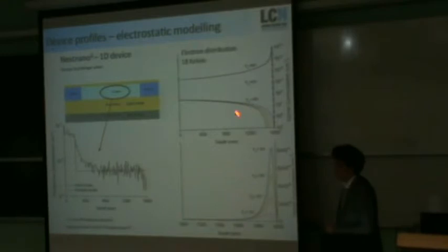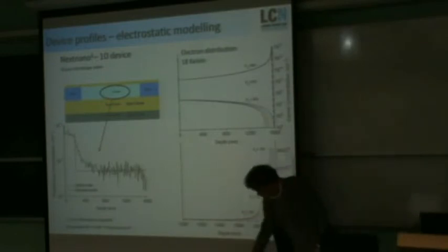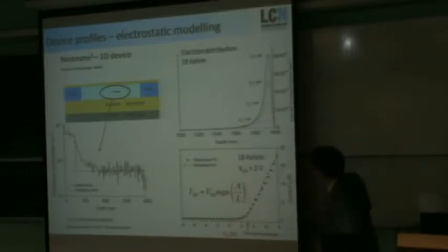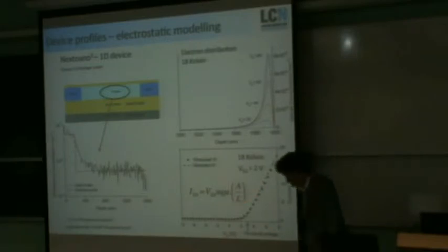You get a depletion region with a negative bias and, obviously, accumulation with a positive bias, and then you get this sort of 2DEG forming far from the actual phosphorus region, the peak phosphorus region, towards the buried oxide layer here. So with this in mind, you can actually model it quite simply just using a normal transport equation and fit these IV characteristics quite simply. And it all fits quite well in terms of the DC measurement technique.